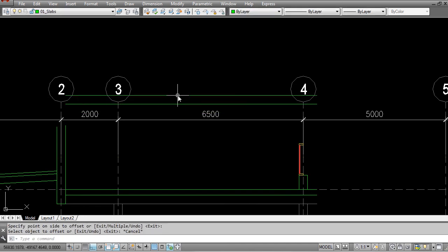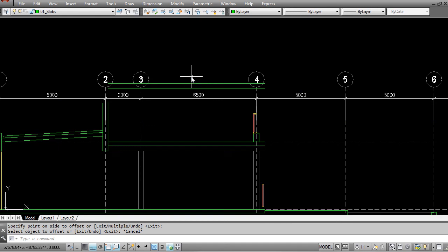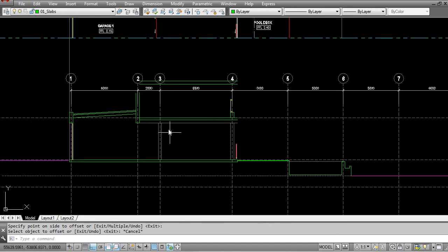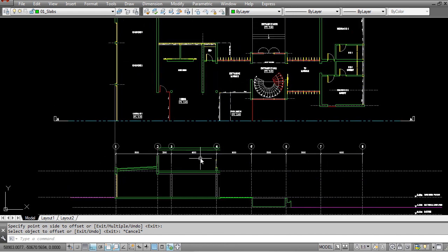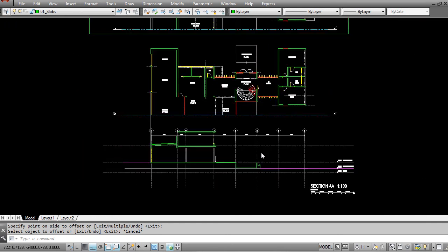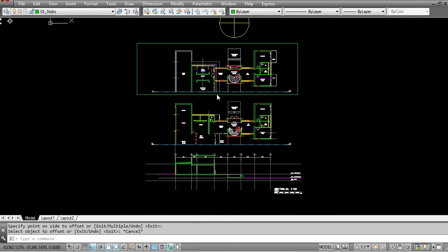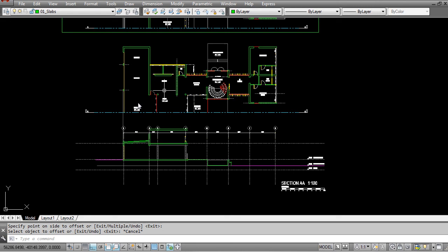So I'm going to say, let's say we have a 300 slab, and we're just going to have a raw concrete finish underneath that. I again could go and change it, but basically what I'm showing you are the offsets that you're making and the way that you start designing your space through your section, which means that you can then take information from the section, for example this information here, and you can then carry it across to your original plan and start to draw in those lines. So therefore what happens is that you start working in between your plans, in between your sections and your elevation, and everything starts to work as a whole as you evolve your design decisions.